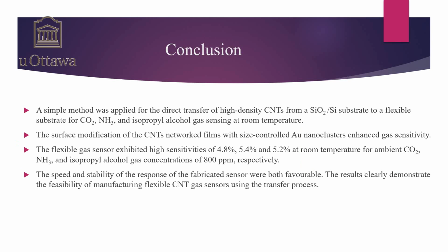To conclude this presentation, we can see that a simple method was applied for the direct transfer of high density CNTs from SiO2 or Si substrate to a flexible substrate for carbon dioxide, ammonia, and isopropyl alcohol gas sensing at room temperature. The surface modification of CNT networked films with size controlled Au nanoclusters enhanced gas sensitivity. The flexible gas sensor exhibited high sensitivities of 4.8%, 5.4%, and 5.2% at room temperature for ambient carbon dioxide, ammonia, and isopropyl alcohol gas concentration of 800 ppm respectively.